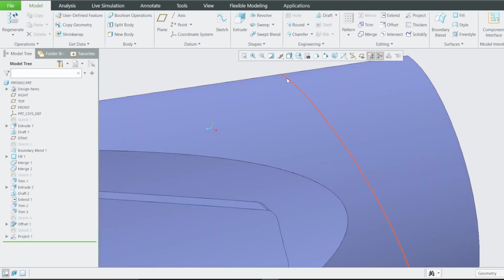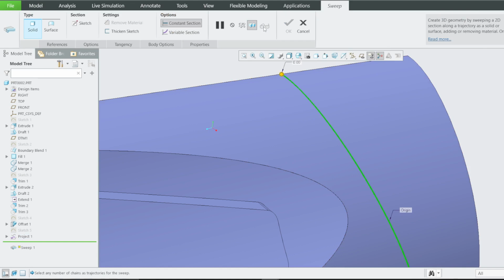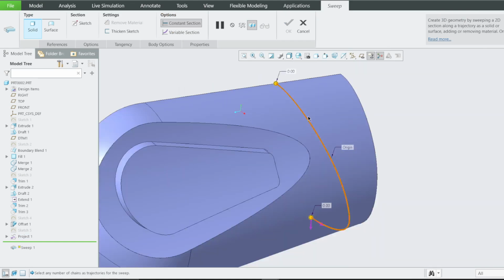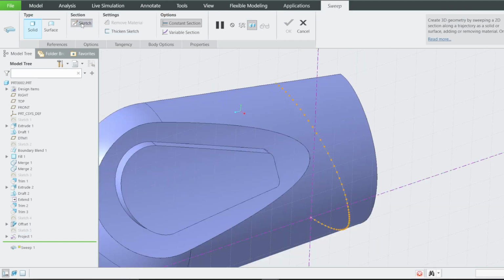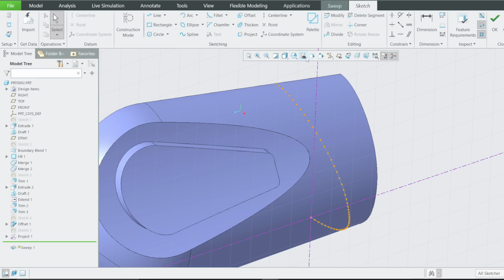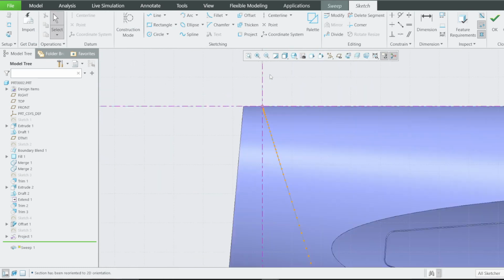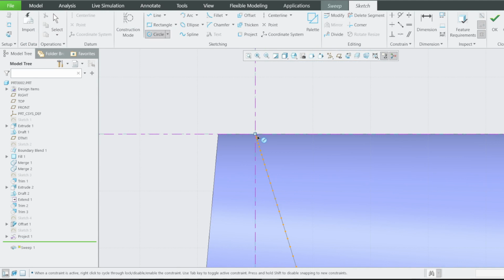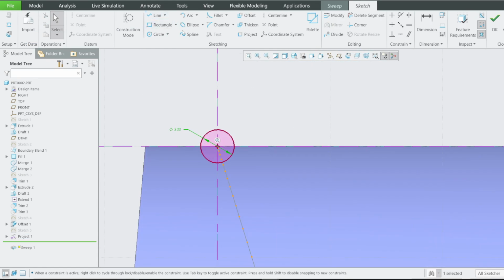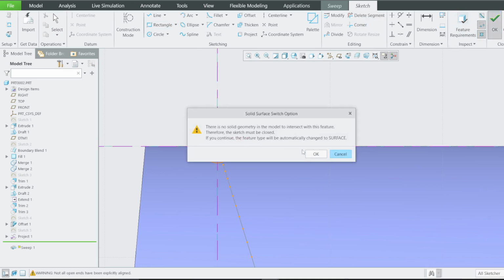Next, we need now to sweep. We are going to sweep here, then trim, then merge. Select your sketch and select sweep. I'm going to sketch here, therefore select sketch and go normal. Therefore I need a circle here. Let me use 3. Then I want to trim the top side, because I just need to have a circle like that.